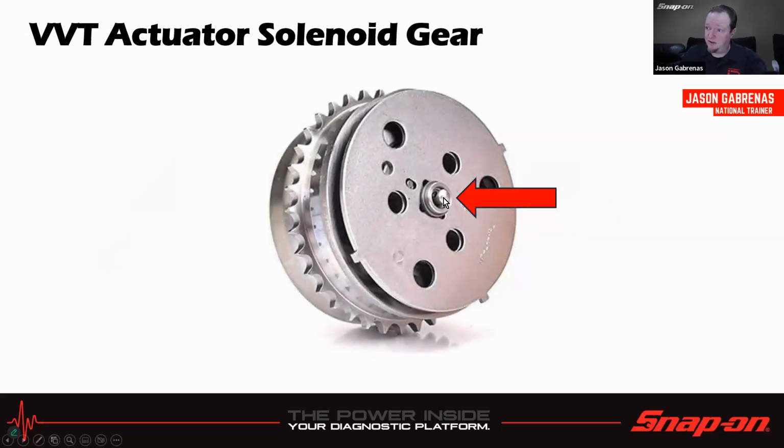So in this case, the spool valve is actually integrated with the timing gear or what have you. So it pushes on that and it moves that in and out depending on where it needs to be, where I need to advance or retard the timing, and that just kind of spins there and just pushes on that little dot as it's spinning by.